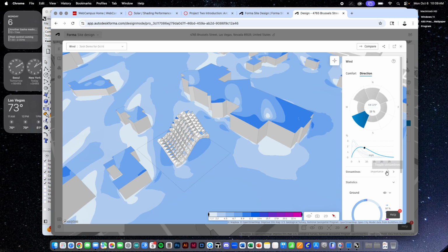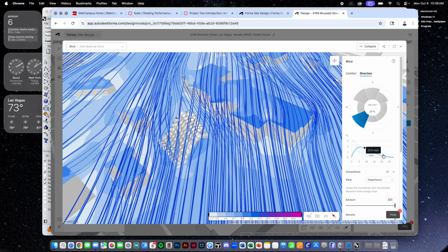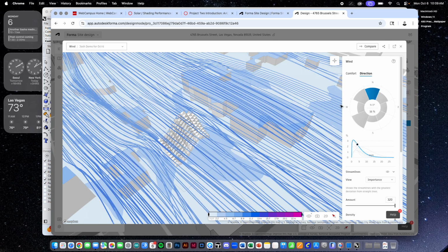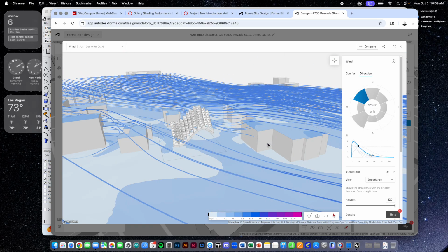But you can also turn on the streamlines, which I found really great to understand where you have blocks, where you don't have blocks, and begin to look at the key directions and try to understand where wind's going to affect you or where it's not, right? That's really important in urban conditions, or our condition here on campus where we have lots of buildings around us. Have you guys talked about this at all? Probably not, right? So wind is a fluid. Air is a fluid that moves. In fact, this is basically a digital version of a fluid mapping table.